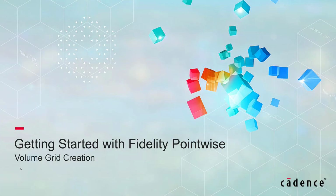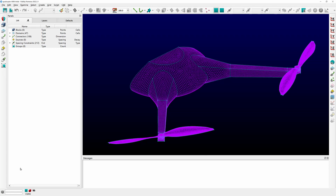Welcome to this Fidelity Pointwise tutorial where we're going to show you how to create a volume grid with minimal effort. I have in front of you the screen of Fidelity Pointwise, and as you can see, I have already loaded a file with a surface grid for half of a quadcopter ready to go for the creation of the volume grid. So what I'm going to do here is to select all my domains